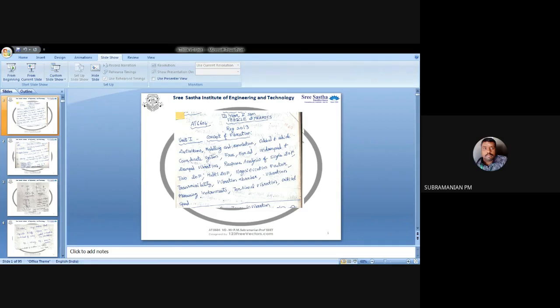We have seen some definitions in vibration, that is, amplitude. What is meant by amplitude? Angular frequency, and the different types of vibration: longitudinal, transverse, as well as torsional. And we have studied critical damping, that is the correct amount of damping that is required to bring the system to the initial position without oscillation. That is termed as critical damping. Then we discussed what we mean by damped natural frequency.